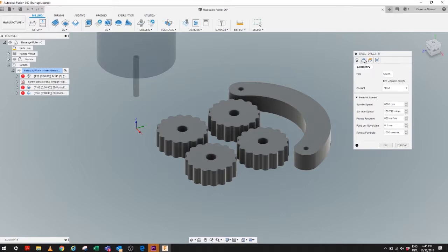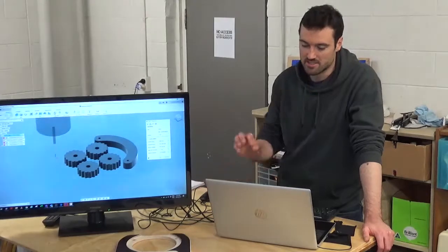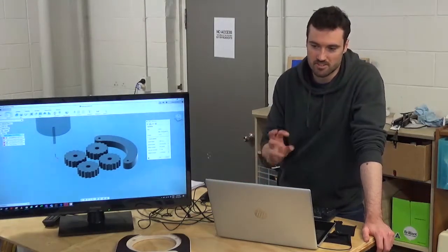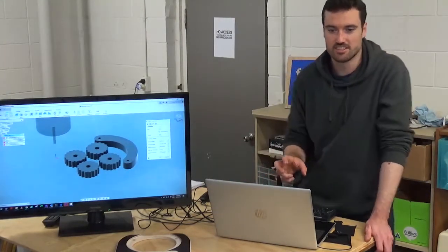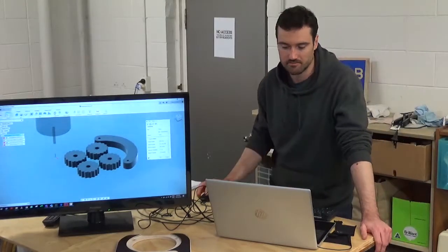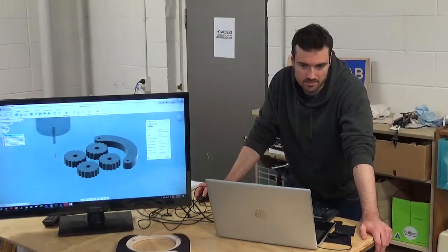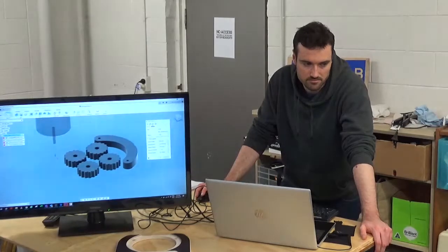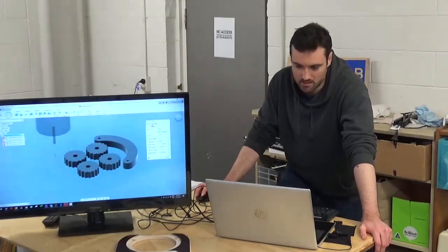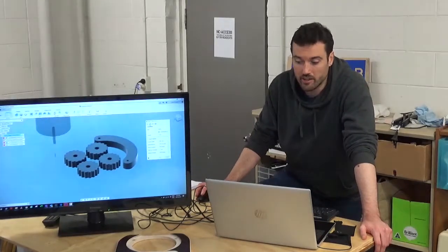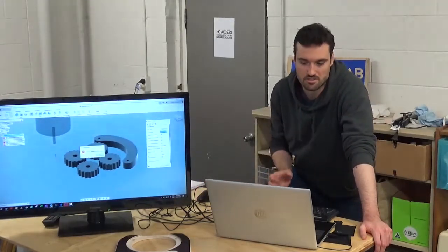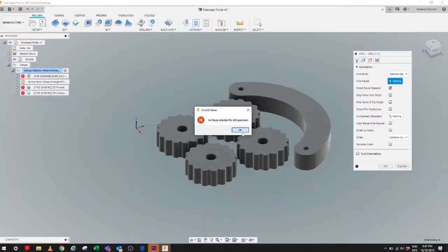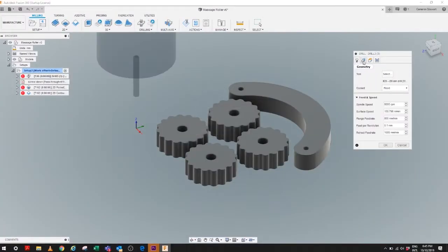And there's a few other bits and pieces. Are these all default? These are set, but there's not too much science to it, to be honest. If you were cutting aluminium, that would all be different, or a harder or softer material. But because we generally only cut 18mm plywood, we just use these values for everything, because we're using the same material, but also we don't know better.